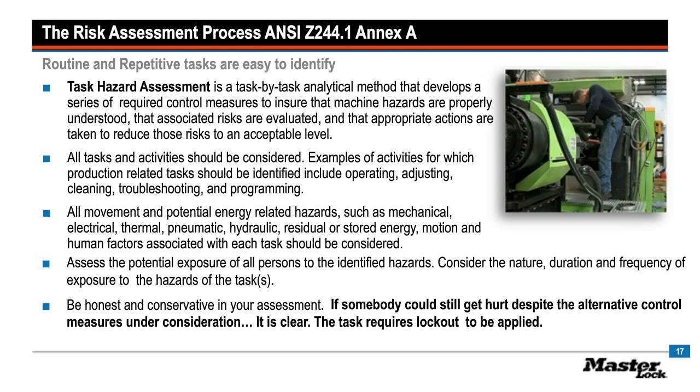All movement and potential related energy hazards, well beyond electrical. You know, the mechanical movement, the heat conditions, stored energy, motion, elevated parts that could move and associated with gravity, and human factors associated with each task should be considered. And again, the guidance is provided within the standard through the forms that we've provided, through the descriptive information in those industry-specific sections as to how that applies to different jobs that are being done.